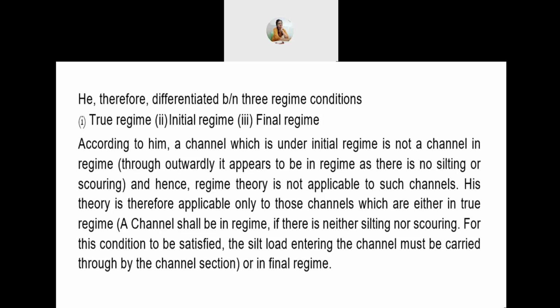His theory is therefore applicable only to those channels which are either in true regime or in final regime. A channel shall be in regime if there is neither silting nor scouring. For this condition to be satisfied, the silt load entering the channel must be carried through by the channel section.